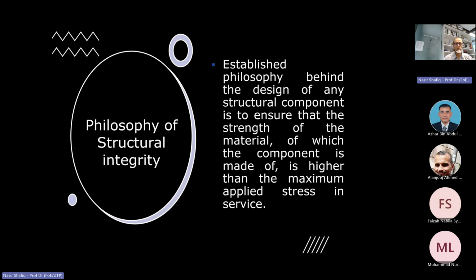As I have given you the example, if the corrosion spot is 20% of the wall thickness, the pipeline has lost 20% of its capacity. If it will be running at the design maximum operating pressure of 200 bar, its strength is not complying with that, which means the failure will occur, right?